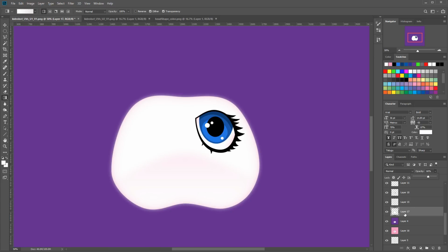And then what you can also do is you can basically make this layer use the mask of the layer below on top of it. So if you hold Alt, you can see how there's like a little arrow down appears when you mouse over between the two layers. You click that, and what it does is that little blurred edge will only appear on this layer, and it will be cut out of the alpha.